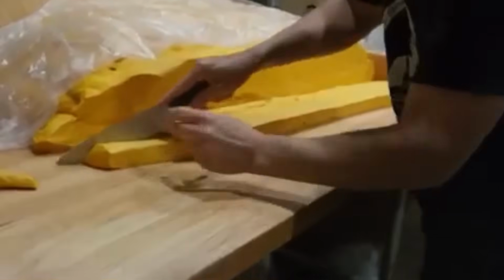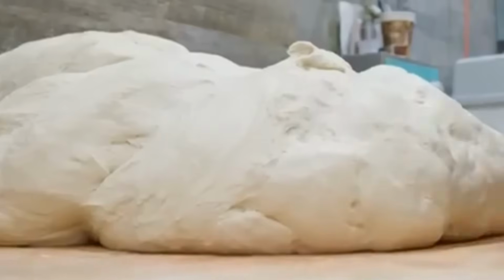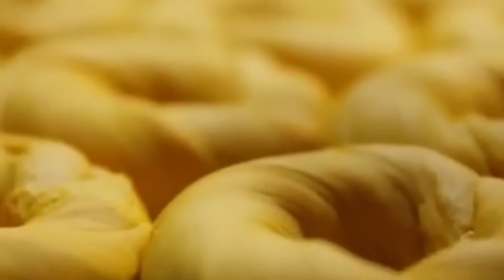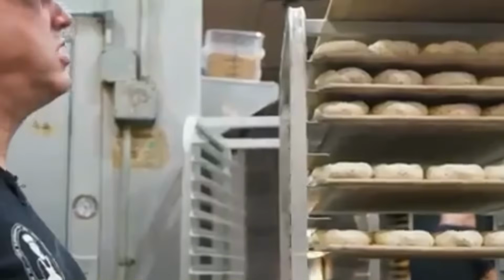These portions are then carried forward to the bagel former, a specialized system unique to this category of baked goods. Here, each dough piece is rolled into a rope between two textured conveyor belts, gradually tapering the ends for seamless closure. The ropes are then transferred to the forming drum, a rotating cylinder fitted with a center plunger and an outer ring guide that picks up the rope, curls it into a circle, and presses the ends together into a seamless loop without pinching, tearing, or folding.